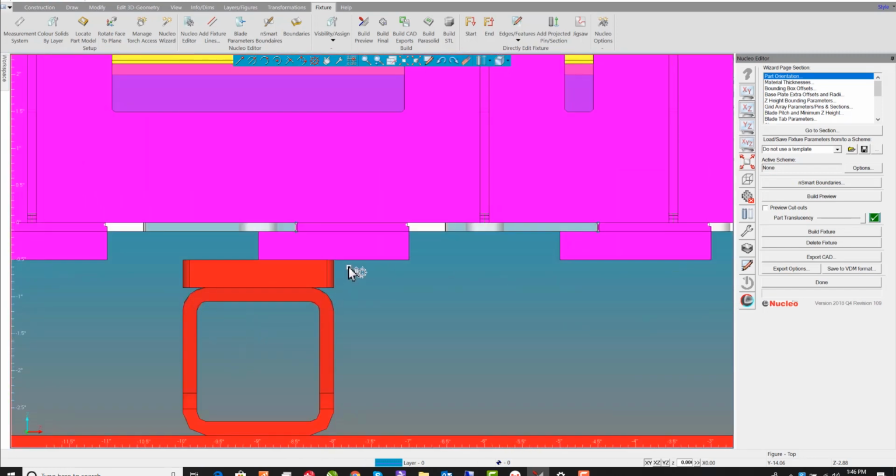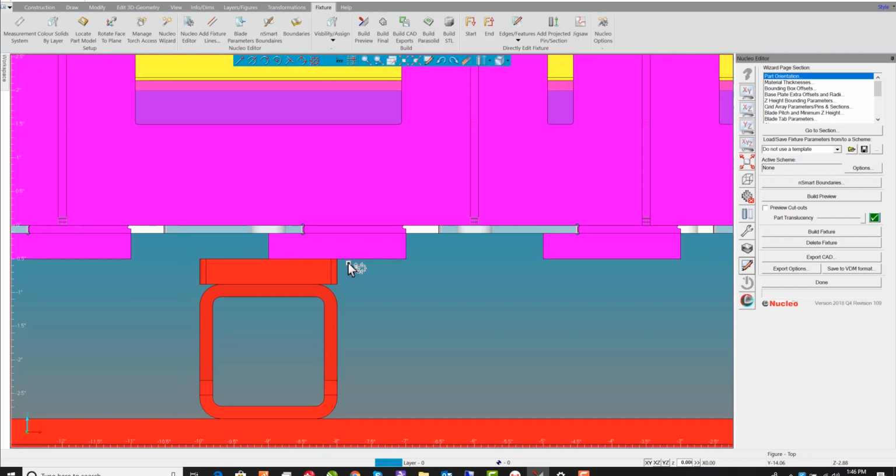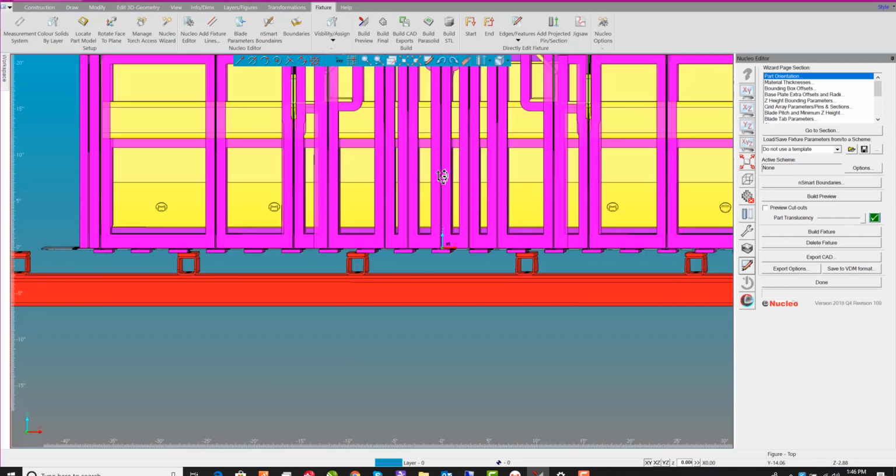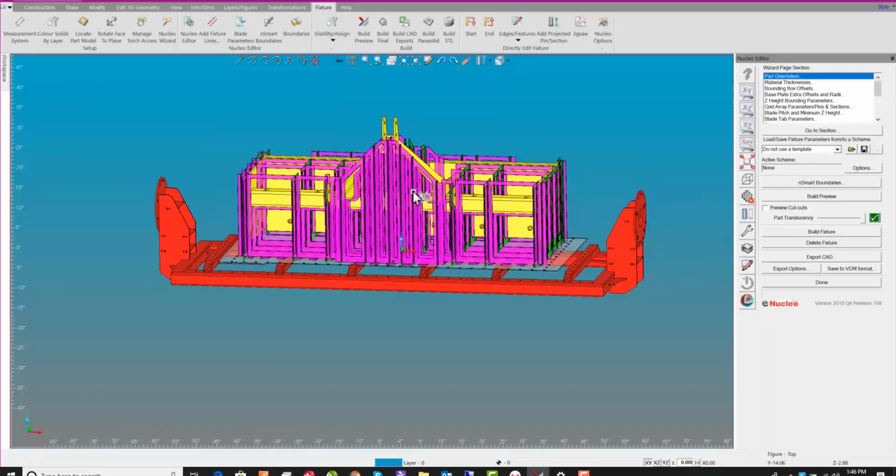As you can see, if I look at it in the XZ view, you can see the tab feet that are interlocked to the base plate. So they go in, and then the whole assembly is shifted to the left to lock it down. Again, you could just have these be blind or just rectangular and flush to the bottom of the base plate.